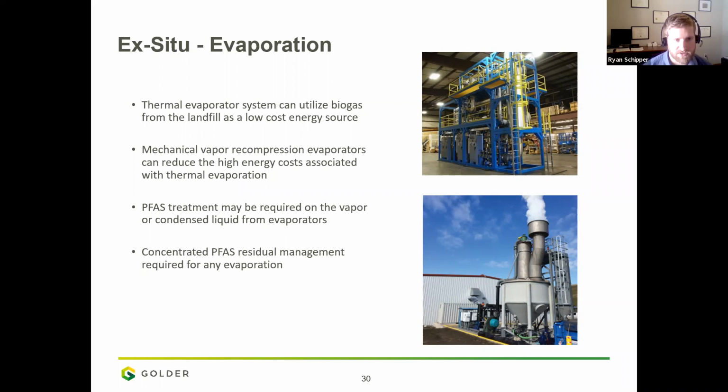As I mentioned, treatment may be required on the vapor or the condensed liquid from these evaporators. And even with that treatment, at some point you can only reduce it so far, and you have some concentrated PFAS residual management required.